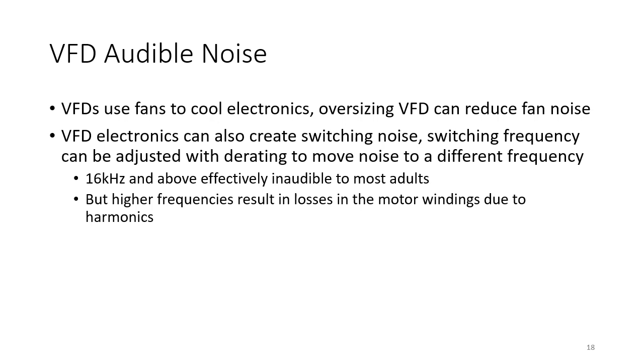There are 2 issues there, of course. One is you've got to have a VFD which can cope with the 16 kilohertz. You've got the derating issue, and the other challenge is higher frequencies. Because those frequencies are still going into the motor, but they're not causing motor movement, they do result in losses in the motor windings. So you effectively get more heat inside the motor being generated without any benefit from extra performance for the motor. So there are downsides as well.